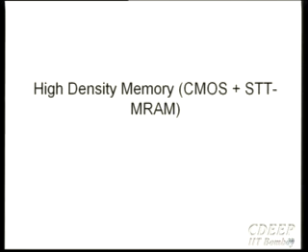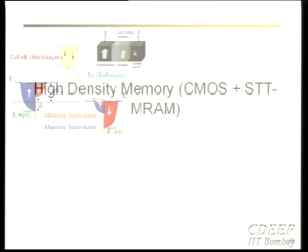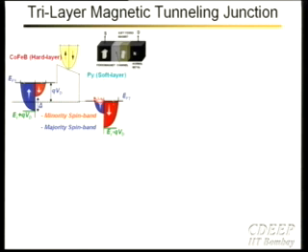And so in this particular case, what we looked at is spin torque MRAMs, and there's a reason why people are looking at spin torque MRAMs as opposed to the standard MRAMs. Any device that you look at has to be more scalable, and it turns out the spin torque MRAMs are more scalable than the standard MRAMs which are available today. By the way, this is one example of a beyond CMOS kind of device from the spin domain. I'm going to be talking about some of the spin stuff in Tuesday's lecture.